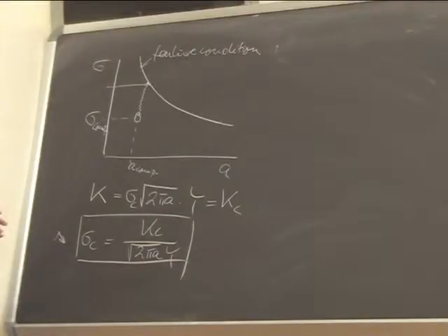There are several measures that can be taken. Either you have found a crack and you repair it, you do a repair weld, which sometimes makes things worse than ever. When the crack is in a weld and you do a repair weld within a weld, this has to be carefully repaired, particularly if it's a thick section.